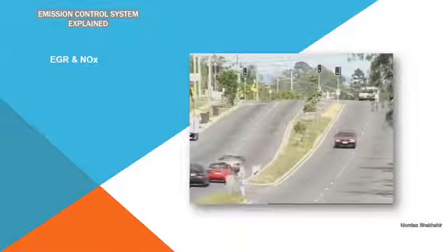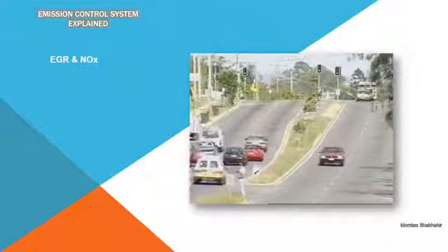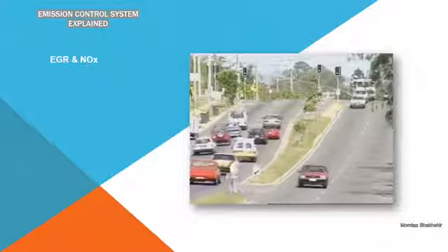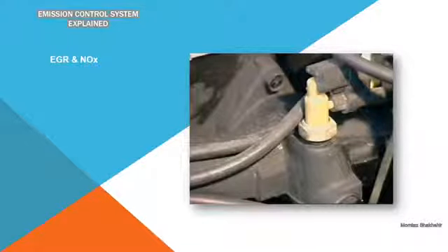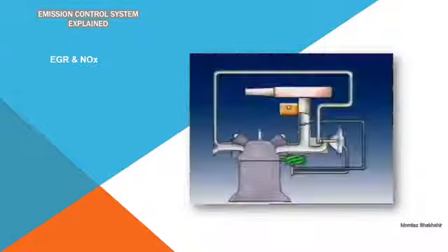The EGR valve usually opens when the engine is at normal operating temperature and likely to be using a lean mixture. When the engine first starts and until it warms up, a temperature-sensitive valve prevents manifold pressure reaching the EGR valve and stops it from operating. Manifold pressure reaches the valve when the engine is warm and when the EGR port of the carburetor is influenced by the position of the throttle. This is generally at light throttle openings, when a lean mixture could cause increased oxides of nitrogen. It does not operate at idle or at wide open throttle.